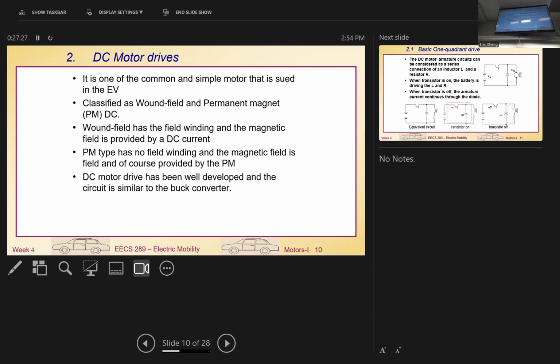So we have to reduce the current or reduce the field. For a wound field system, you're able to control the magnetic field, but for PM we cannot. So the PM motor, in a way, has less advantage when we control the motor to very high speed. That does have some disadvantage. Later on, we'll show you some charts so you can understand the advantages against each other.